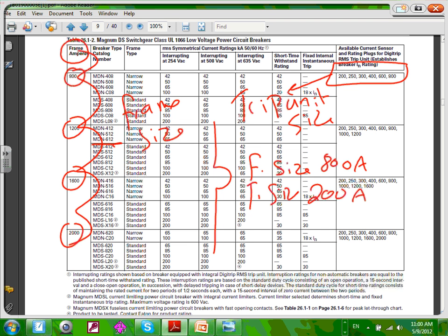How are you going to size the circuit breaker? The cable. Which number are you going to use to size the cable? The trip size. On the face of this circuit breaker, guys, they have a unit that you can plug into the face of the circuit breaker. That trip, you can make the 800 amp 200, or you can make it 250 or 300 or 400 or 600 or 800, based on the literal electronic equipment that you plug into the circuit breaker. It gets more interesting then.